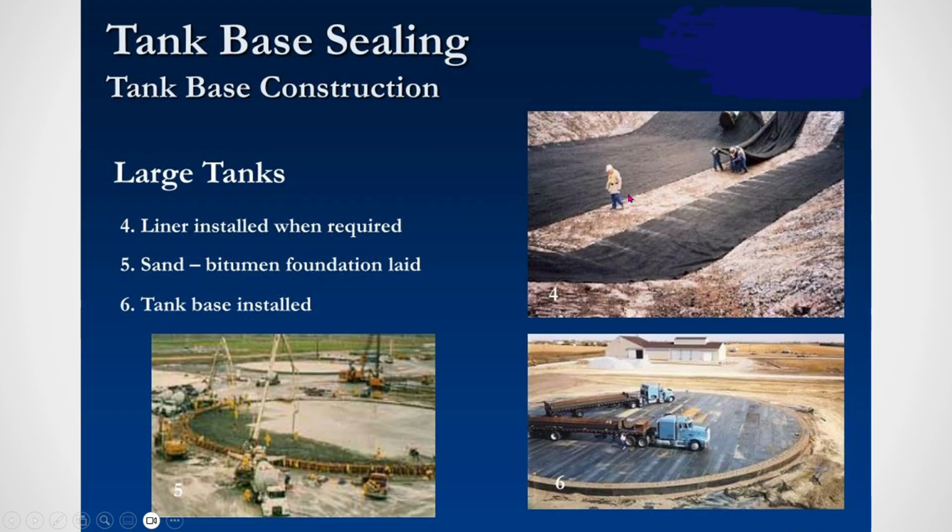It is called the liner. This one, the black one, is called the liner. It is PVC sheets, simple HDPE sheets. They were provided on the gravel bed, and then above the liner we are providing the bituminous sand, so that there will be uniform compression loading when I place the tank.